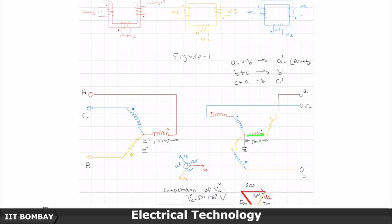With this one winding I have connected another winding, that means the B phase winding. I have connected them in series, such that the voltages sum upwards, the phasor summation of the voltages happens, and that I have taken out to the A terminal. Both sides are grounded, the neutrals on both sides are grounded. So the A secondary and B secondary are connected in series and then they come to the A terminal. I have written A plus B goes to A dash. I did not write A because it would have confused.